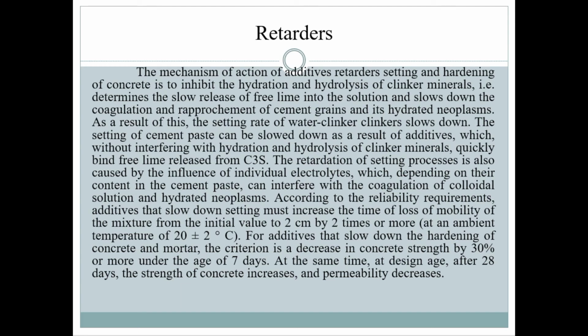According to reliability requirements, additives that slow down setting must increase the time of loss of mobility of the mixture from the initial value to 2 cm by 2 hours or more.